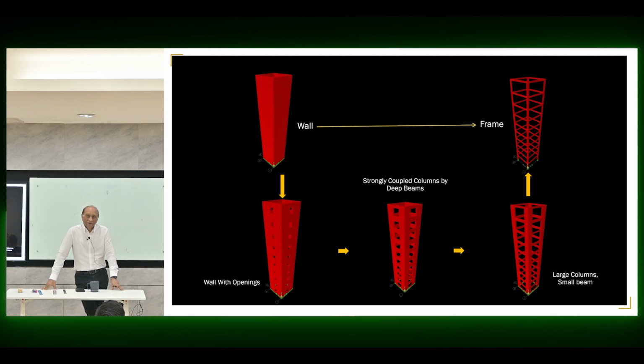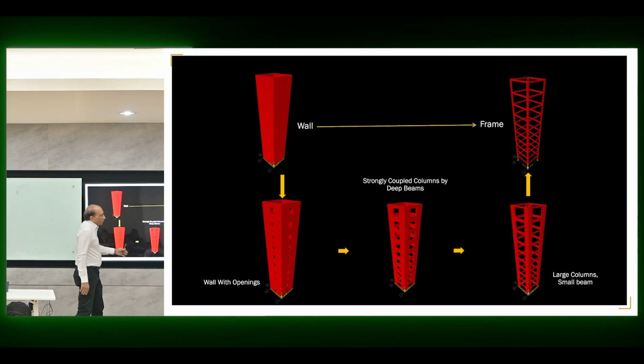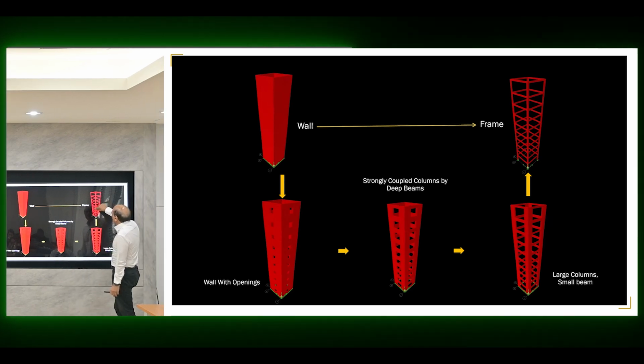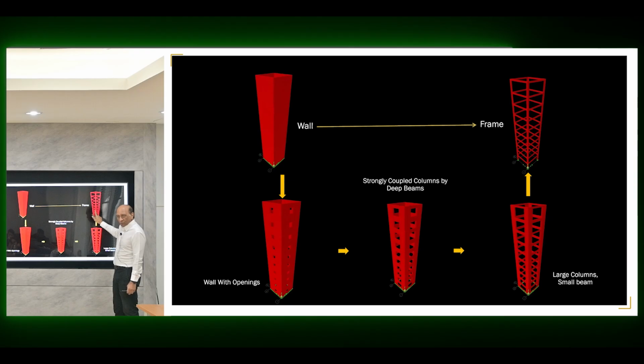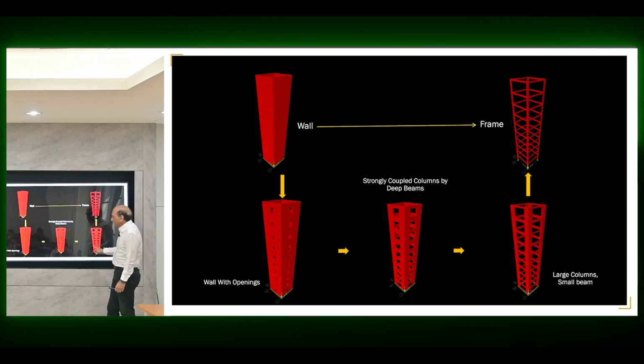Once you do that, you will find that you remove so many issues in your modeling. So that's why I showed you this one, that you can think of them as continuous. This is, of course, a very extreme case. You can see that the size is very large, though you won't gain much advantage by using shell element, although you could easily do that. And here you can't use a frame element. So somewhere there is a gray area.